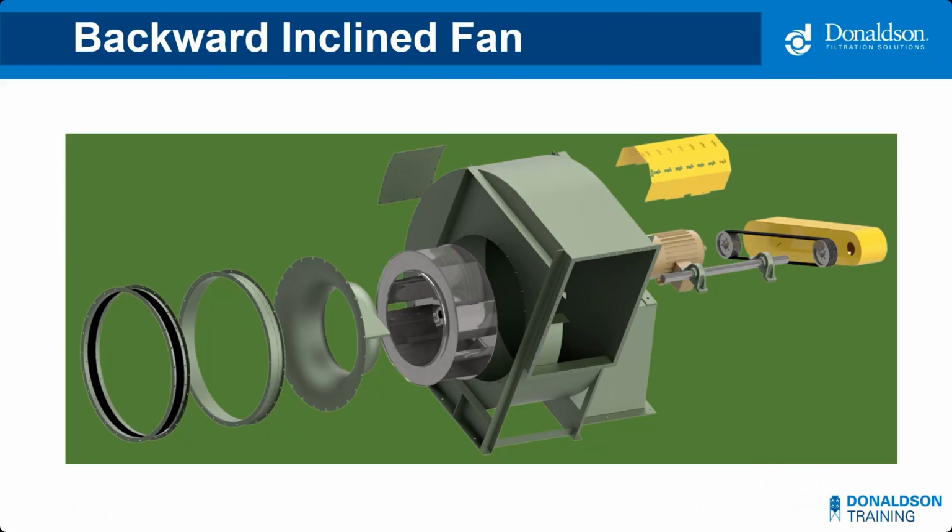Now here's an example of a larger fan, probably a ground-mounted fan. This exploded view gives us a good picture of all the different components. So let me run through them left to right. On the far left, we've got an inlet flex connection, then an inlet flange. That next piece there is the inlet cone that'll efficiently direct the air into the fan wheel, which is the next component. Then we have the fan housing.